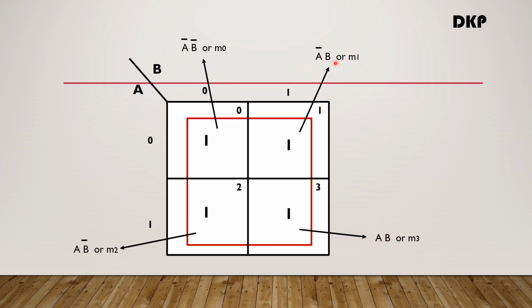And in this case we can retain B when you compare this. So in each case when you compare with the adjacent cells, one variable is differing and the other variable is constant. Therefore this F5 is equal to 1. That is, all these terms will get reduced to 1.